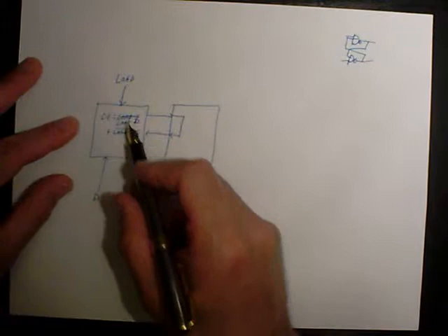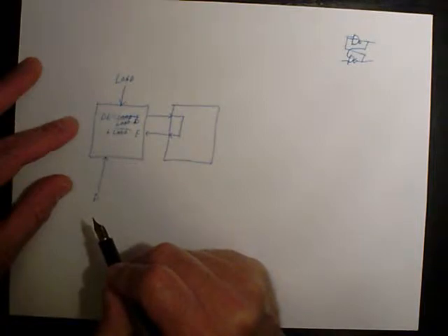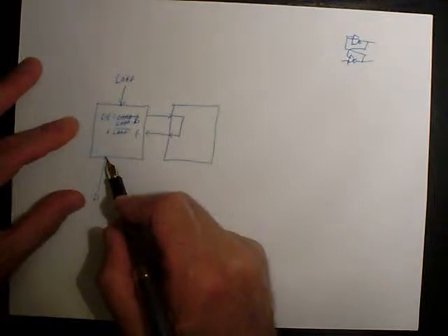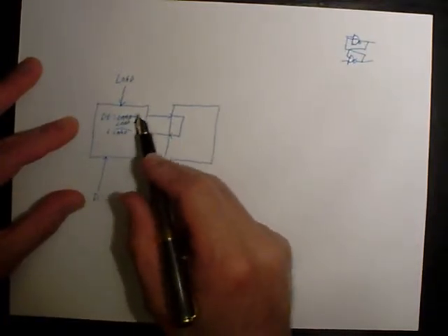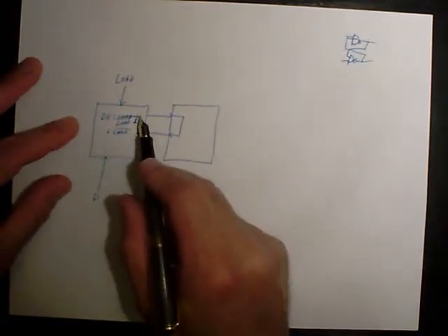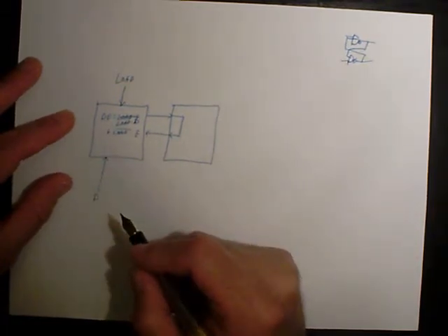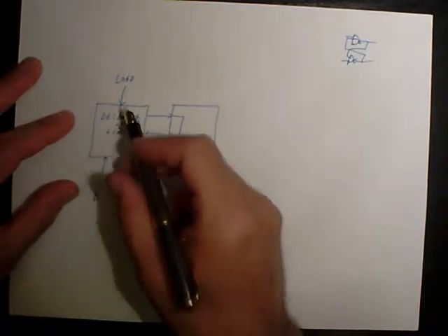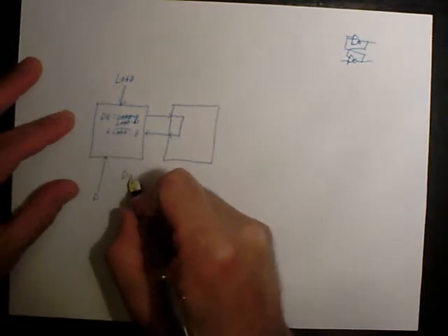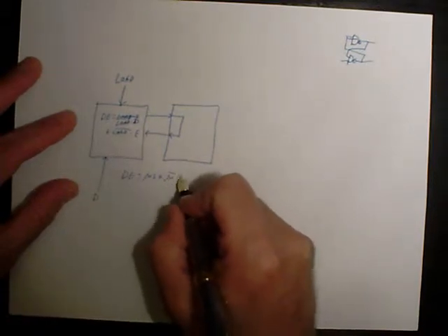So whatever data we have coming in here, if load is low, simply gets circulated back through here, and we have a bit trapped between these two cells. But if we raise the load line, then the data coming in from the south, this D line, gets sent through to the east and comes back in, and then when the load line drops, the last value that we had coming from the south will start being trapped in here and will circulate, and so we'll be able to load a value into this two-cell D latch by putting a value on D, raising the load line, and then dropping it. So the actual Boolean equations in here would be something like data east equals north-south or north bar east.